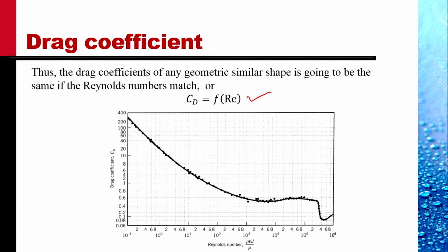An interesting thing to notice, however, is that over a large range of Reynolds number, from about 10 to the power 3 to 2 into 10 to the power 5, the drag coefficient is effectively independent of Reynolds number. This fact is of great importance. In fact, you would see tables in handbooks for drag coefficients where the Reynolds number is